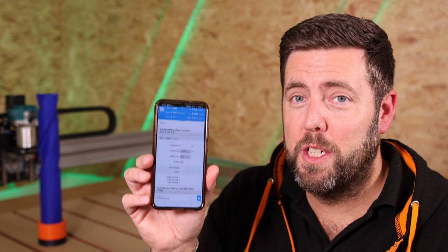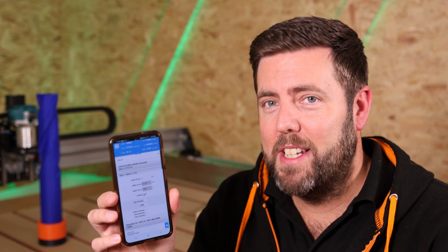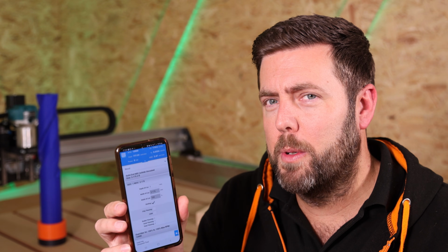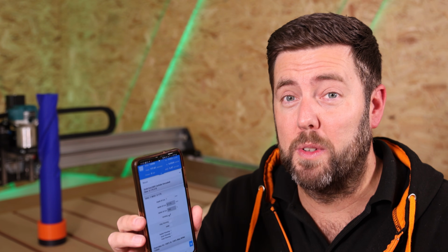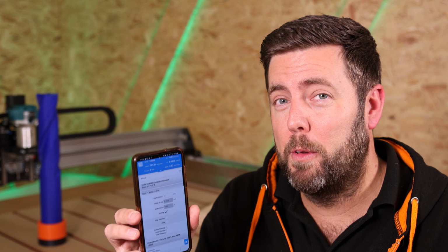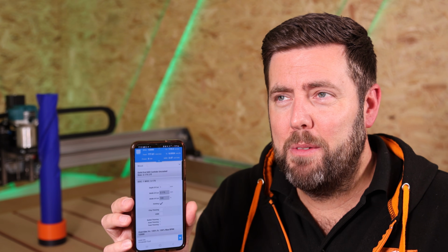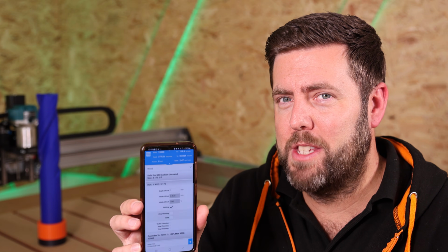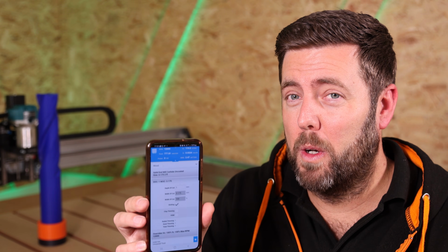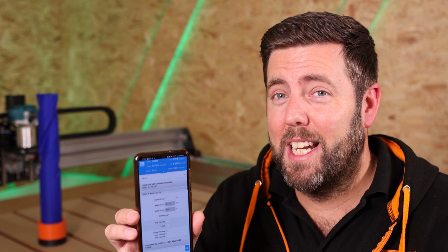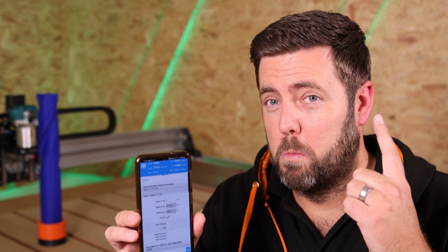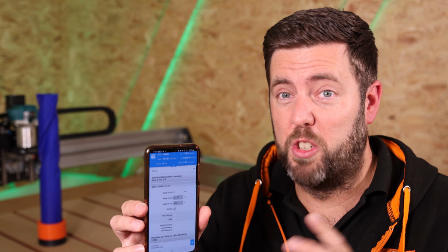Next, we're going to switch over to FS Wizard. Now, the advantage to this is it has more variables that you can change for different controls. For example, you can select different type of bits in this if you wanted a ball bit, for example. However, its downside is that it's probably more for metal machining than CNC woodworkers. And what I mean by this is it basically gives you one option for wood, just wood. No softwood, no hardwood, just wood.